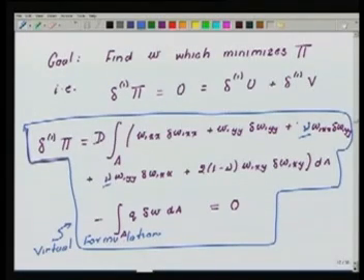So once we have this formulation, now we are in business. We can solve the problem. We have not yet done any approximation here. We have simply posed the definition, or representation, of the displacement. From there we went to the state of strain, to the state of stress, and obtained the total potential energy, that is, we wrote the functional.